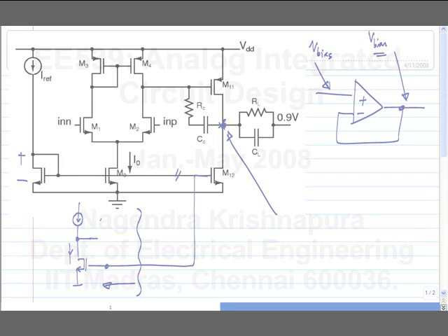so you will use this. We have seen the circuit, right? So which is plus and which is minus? Lower one is plus. And what is this? 0.9. So if we have a circuit like this, then the drain is biased at 0.9 and gate is biased at whatever current and whatever voltage is required to have this particular current density. So the mirroring is exact. Is this okay?